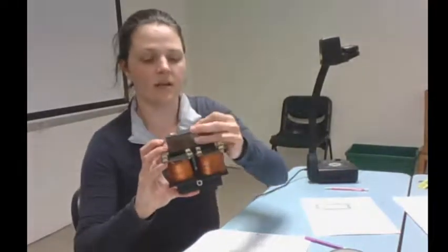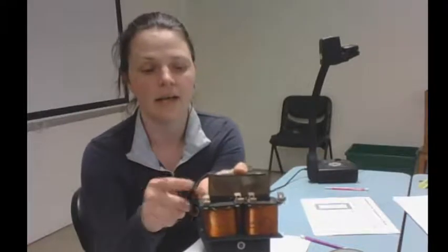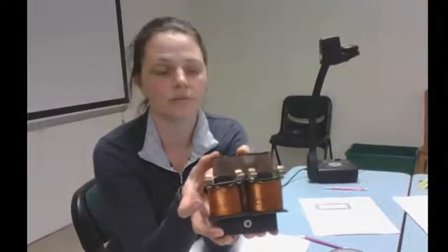If this is the external, primary coil, there's going to be a field here that's going to either go up or down. If it's alternating current, it'll be going up and down and up and down. And this steel helps redirect the magnetic field so that it comes up and around and then down into the second one. This is how we usually build transformers, because it's a more compact way.